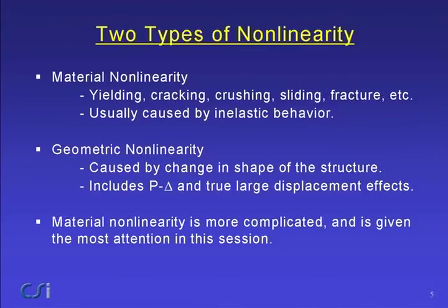Then there's geometric nonlinearity, which is caused by change in shape of the structure. And there are two forms of this. One is the P-delta theory, and the second is the true large displacements theory. And one of the things I'll emphasize is that for seismic analysis, P-delta theory is perfectly adequate.